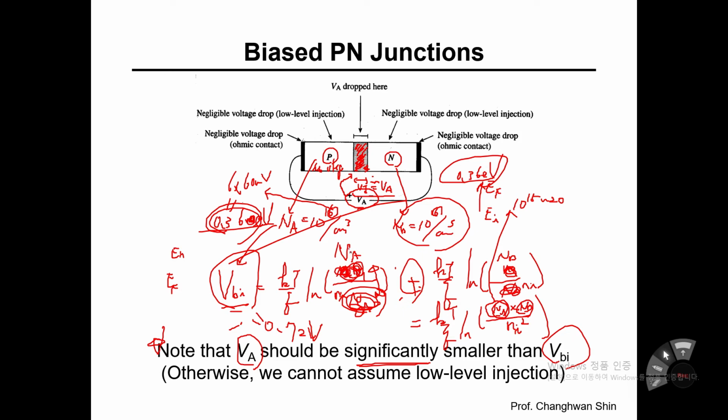Why 0.5? That number is very closely associated with the doping concentration on each side of the PN diode. So suppose that a constant voltage drop of 0.7 volt is assumed in a certain problem set across the PN diode, which means the P side and N side are doped with 10 to the 16 in doping concentration.